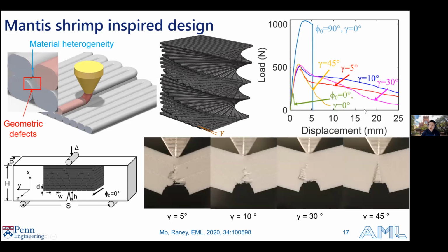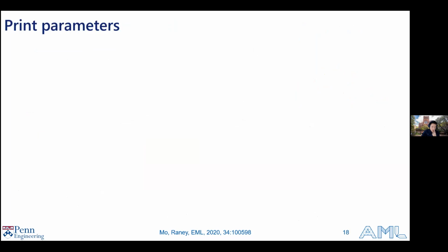However, for the material with these defects arranged in a Bouligand structure, we have very high resilience to crack propagation, where you can actually load this material all the way until it hits the 3-point bending fixture, and we can no longer load it further. So this shows that these structures are very resilient. The crack doesn't propagate catastrophically in these materials.